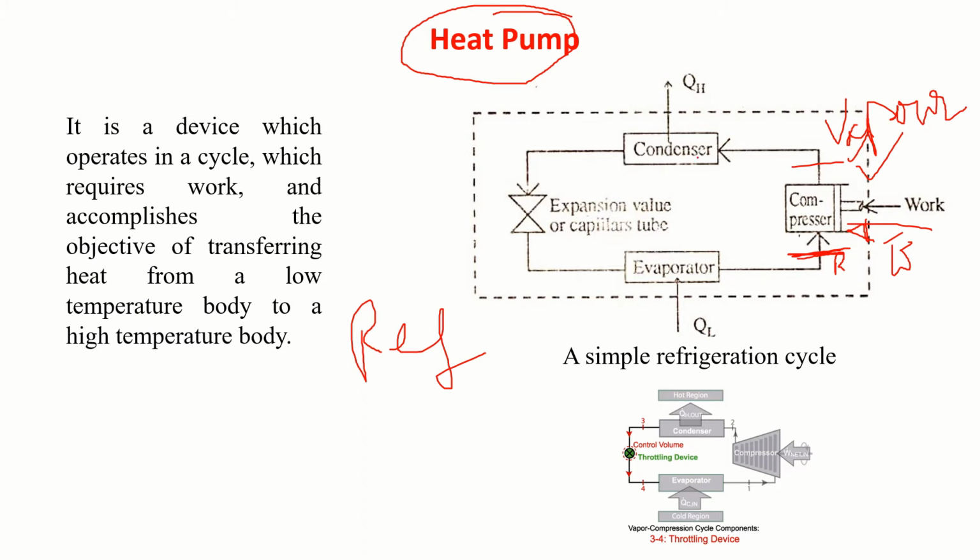Right. This vapor enters into the condenser. Maybe I blow air, or I will have a water jacket circulating around it so that heat is removed from this refrigerant. So that here I'll get high pressure, high temperature. Here it was vapor, but here it is liquid.